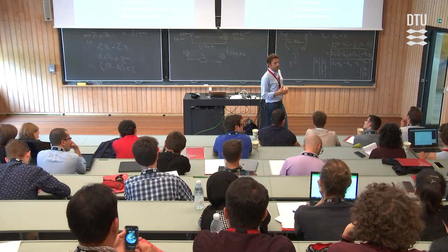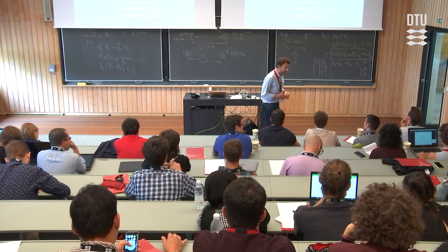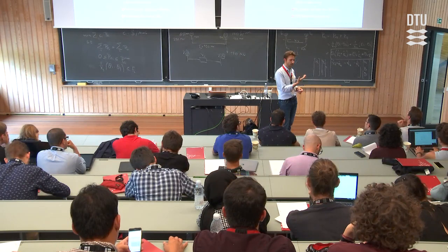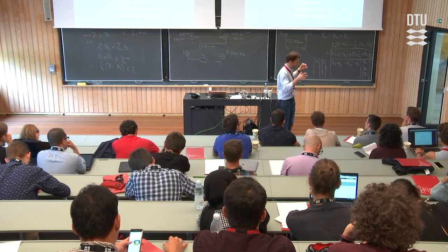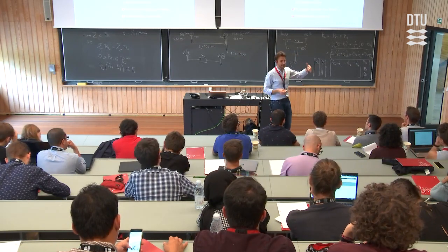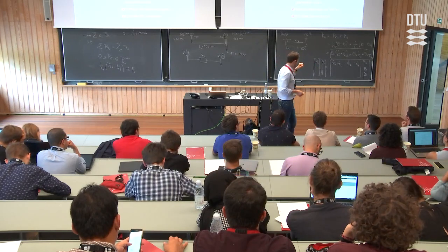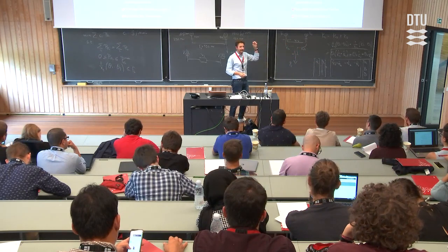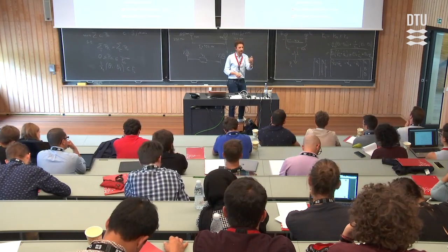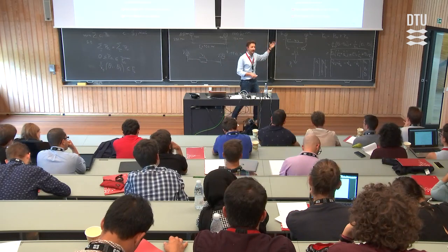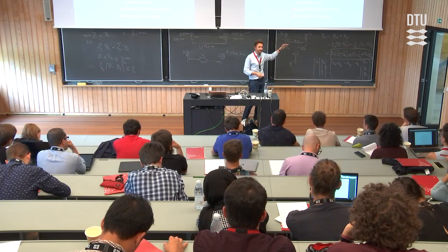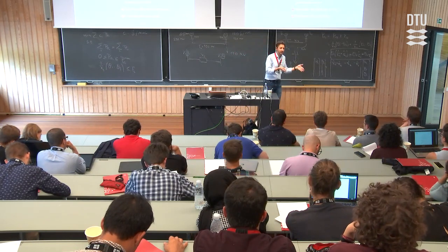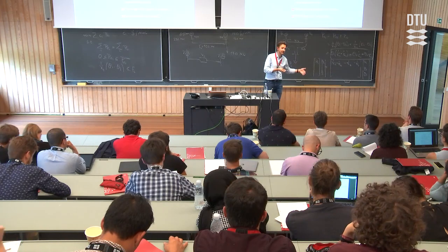And what about the cost? They are also in dollars per megawatt hour? Yes, but you can either have a factor in your objective function to express that, so you can have your base MVA in your objective function. But it's not going to make a difference for your optimization. It's just a constant factor that is going to be multiplied. You can either have it in the objective function, or you can leave it as it is. But at the end, you're going to know that it's not 1.2 per unit. It's actually 120 megawatts, right?